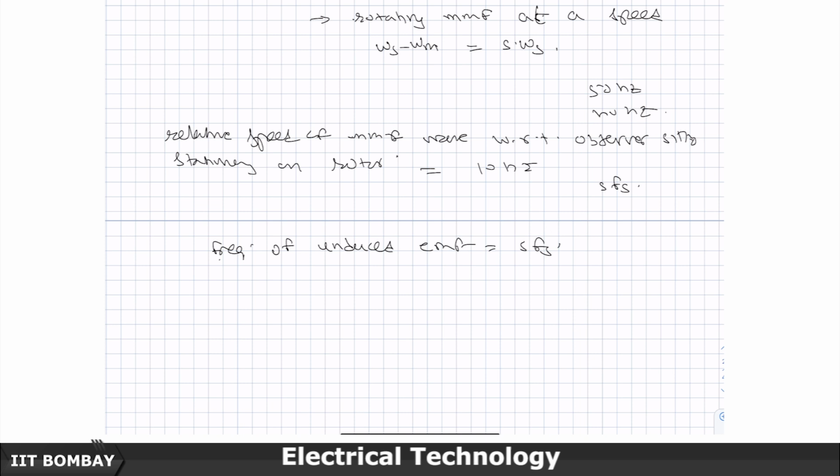Then you will generate a sinusoidal voltage in time in the winding, due to the fact that phi is continuously changing, and phi is BA cos theta and all that. We will come to more details of that, but we have seen that earlier. So the induced EMF depends on the rate at which the flux is changing. If phi is given by phi m cos of omega t, in this case it will be phi m times omega times sin of omega t.